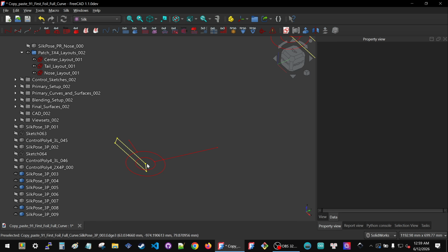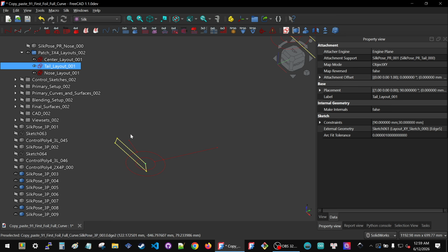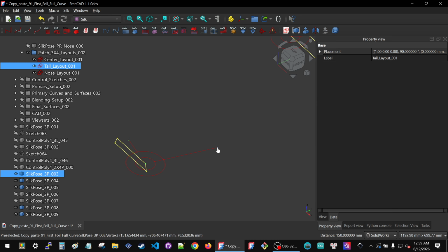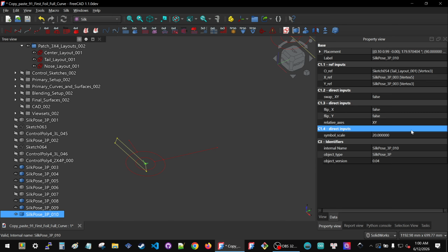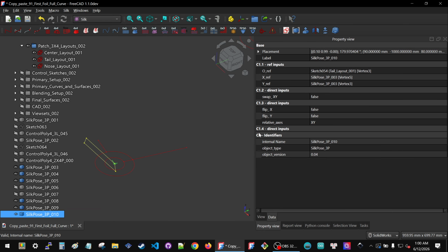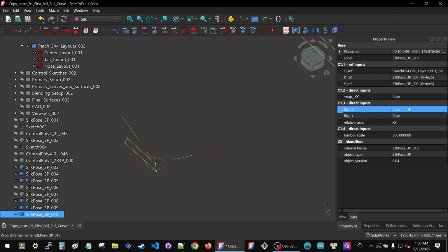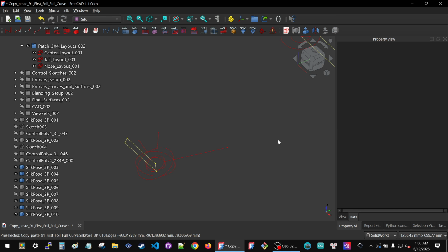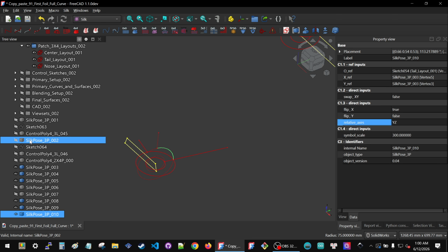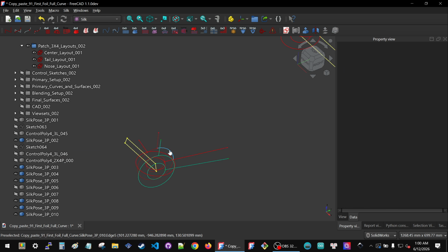Let me hide this, and then we'll do it. This will still be the origin, but now I'm going to start with the X this way, and I put the Y this way. I create the object. Collapse something here. Okay, size 300. I've never seen that section collapse, but it's neat. I guess you double click. Okay, great. Set this one. I don't swap. I flip X. I choose YZ. And that has made it like this one.